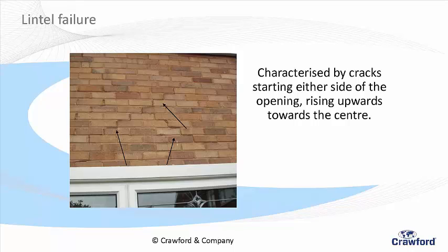We have instances where we've said lintel failure and then we've looked and there is no lintel. So it's not so much a failure as opposed to there isn't one. I think on that as well, you see it in 60s type buildings where they replace PVC from the metal, and a lot of times the metal window is designed to almost replace that. Yeah. Well, we talk about that because I've got bay window replacement, which is what I've classed that as.